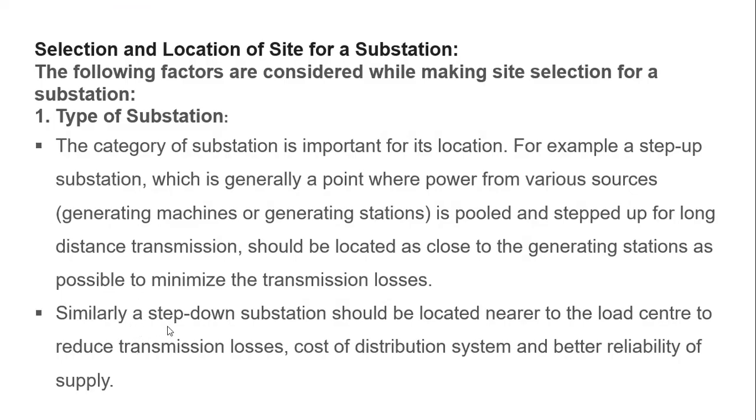Similarly, we are selecting the step-down substations, or we are locating the step-down substations. Okay, this type of substation is to be located near to the load centers. Okay, why? Because being near to the load centers reduces the transmission losses and cost of distribution systems and gives better reliability of the supply.